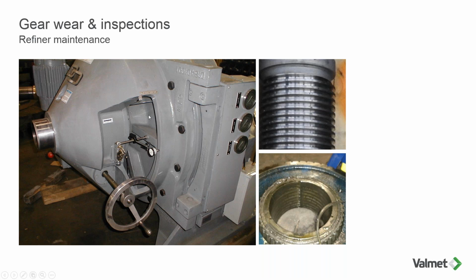This is the only component that actually moves inside the refiner, the sliding head back and forth. We want to see how many turns of backlash the refiner has, or how many turns it takes before there's actual movement in the sliding head.